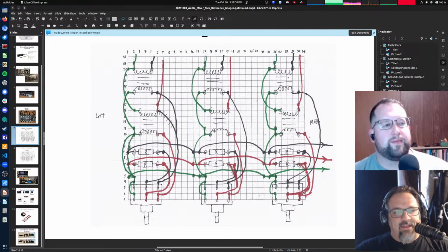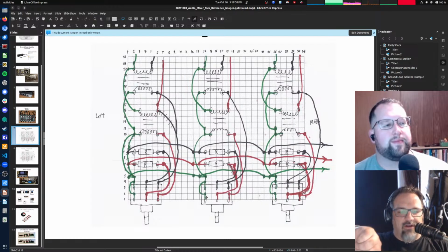All right, and then on the output side of those transformers, your shared ground goes over and connects to the fully counterclockwise side of the potentiometer. And then the wiper, the center part of the potentiometer, is connected to your outputs, which are through these resistors. We'll talk about those resistors in a bit. So the wiper is the output.